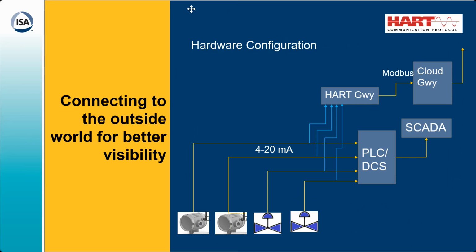But it doesn't affect your 4 to 20 milliamp current signal. So you can add a small resistance into it, and across that you get a HART signal, and the HART gateway uses that HART signal and sends the commands and responses on that 4 to 20 milliamp loop. So no need to change anything in your processes.